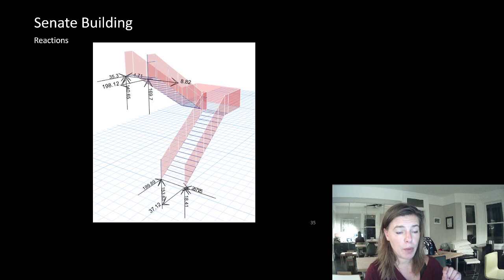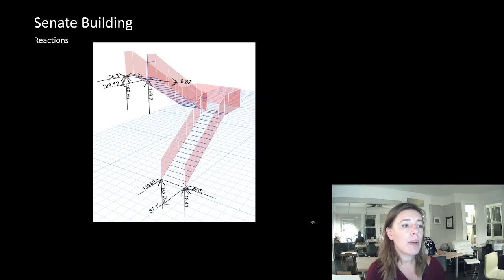That I am comfortable, I'm using my engineering judgment, that being over that 2% is okay. And that's pretty common. Engineers will do something like that a lot. It's about knowing what the element is and what it's doing. If I had a column that was governed by slenderness or in a slender zone, I tend to keep it at about 70% of capacity. If it's something that has multiple load paths, I sometimes might even go as high as 110% of its capacity.